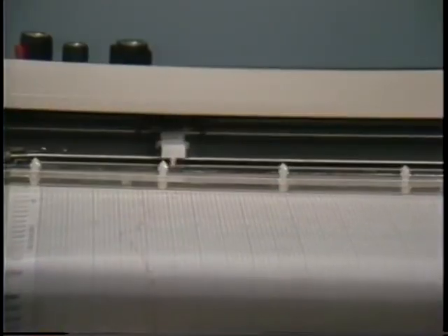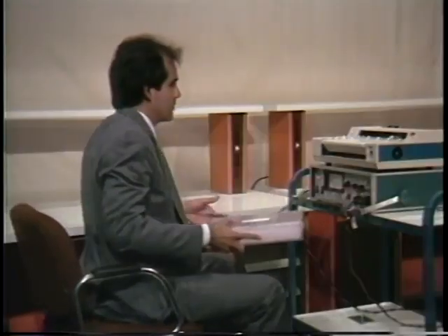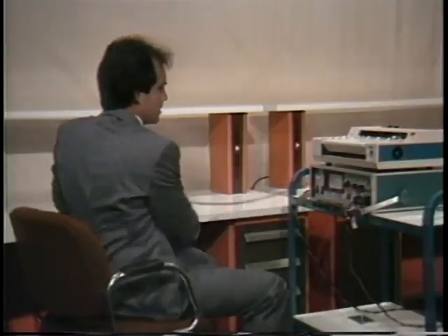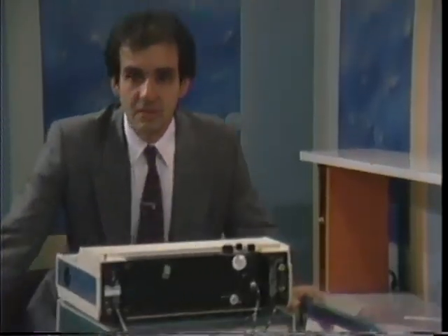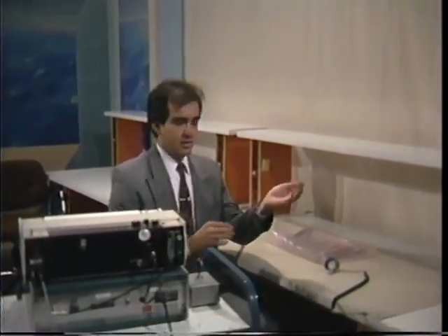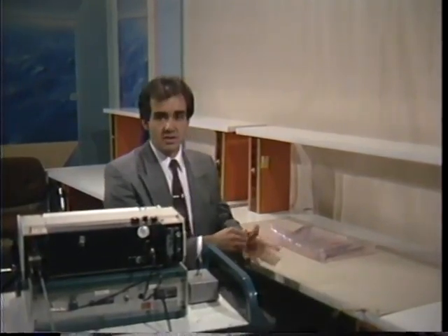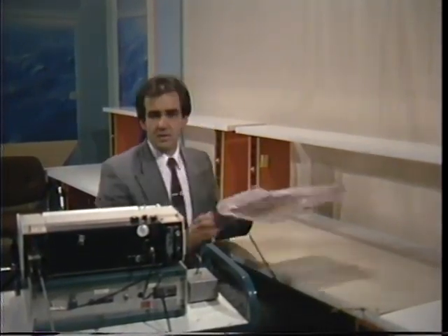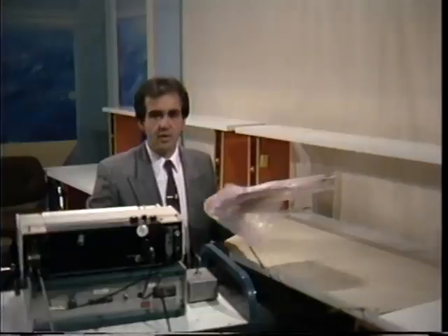Let's look at a workstation with no ESD controls. Using an electrometer, we can measure the voltages generated by an operator's movements. Now, let's compare it to a workstation which has ESD controls. On the surface, they look very similar. Still using the electrometer and grounding myself to the workstation, we see there are no voltages measured from the operator's movements.